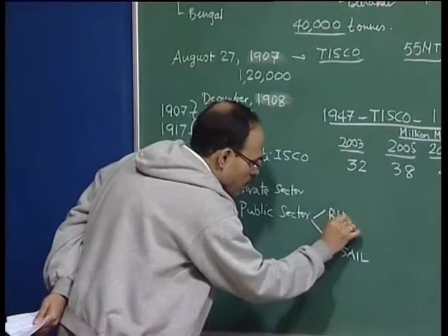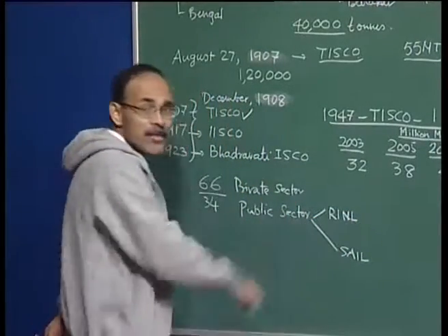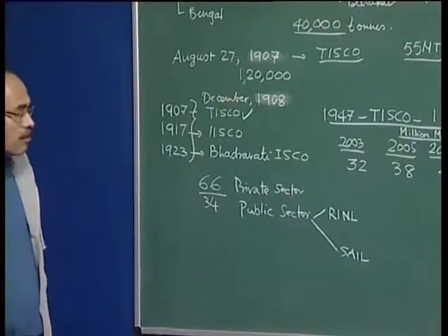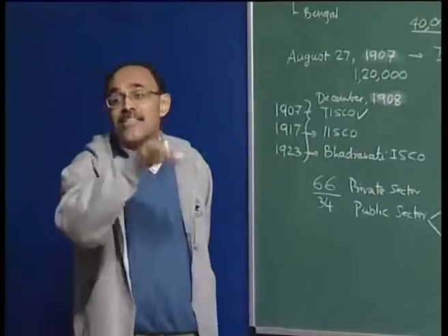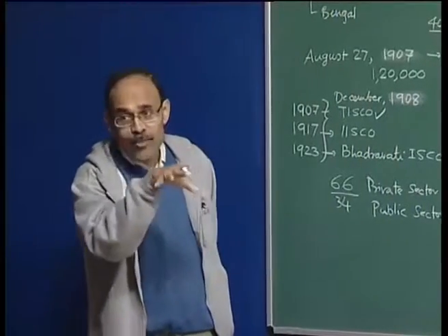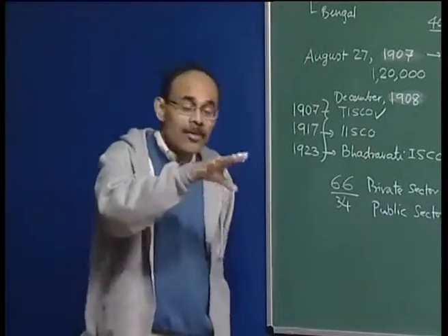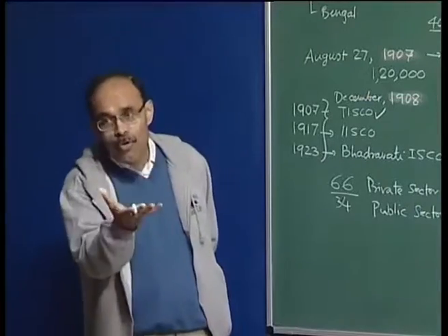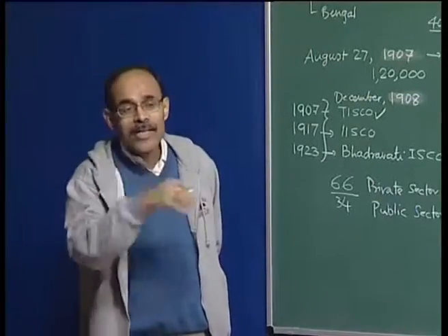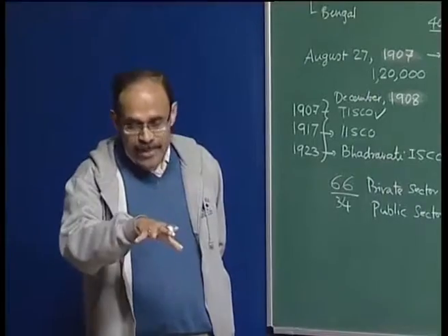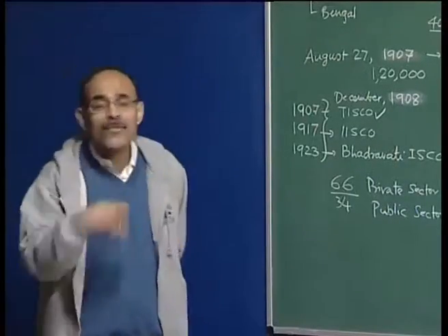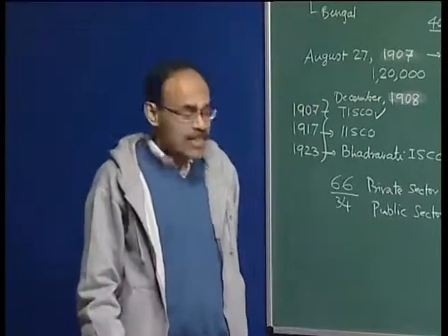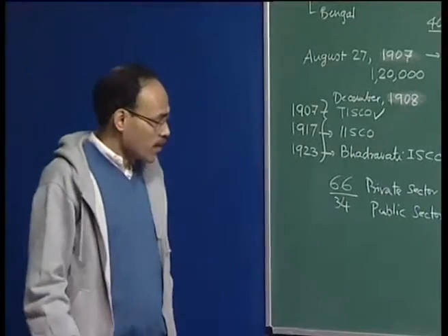These are Rashtriya Ispat Nigam Limited, that is the Vizag based steel plant, and that's what I said. Vizag steel plant is a shore based steel plant. So why is it shore based? Because it uses blending of coal. So you import coal, then you blend it. If your plant is located close to the seashore, then importing and exporting the finished products becomes much easier. Transportation cost is minimal.